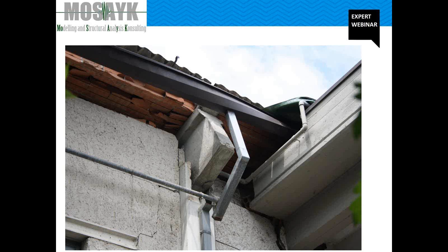The most severe damage occurring during Emilia earthquake was mainly associated with the structural element loss of support and consequent falling, because the beam to column and roof to beam connections lacked mechanical devices, as we can see here, as seismic load transfer mechanism.